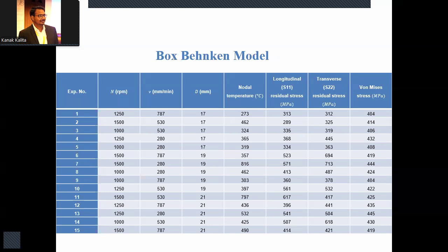we wanted to replace this simulation, because each simulation would take at least 30 to 40 minutes. So we wanted to replace it with some kind of machine learning model, which we call a meta model or surrogate model. But for that, initially we need some pilot data or training data to train the machine learning model. For that, we have used a particular method called the Box-Behnken design.